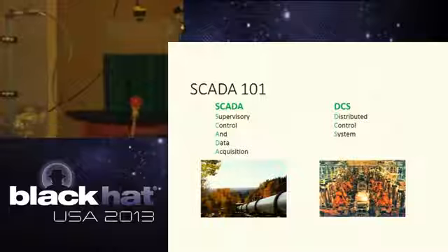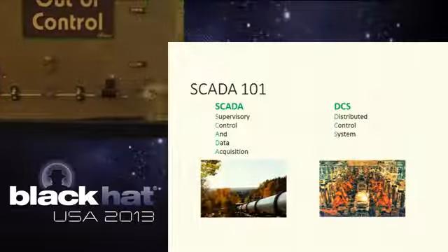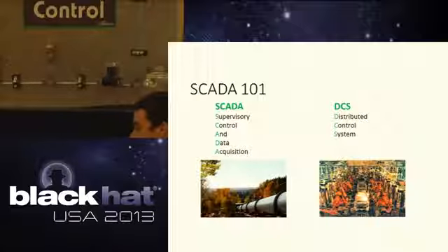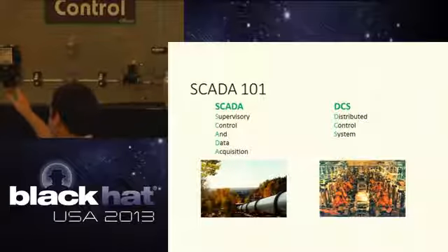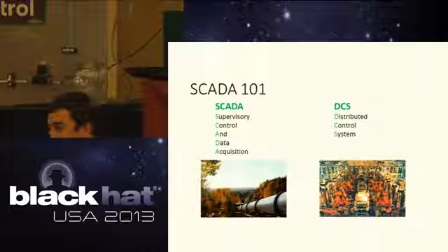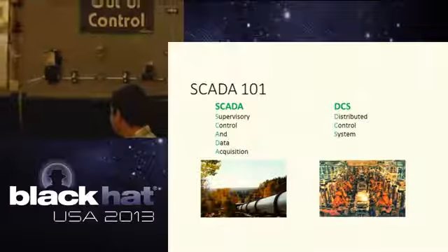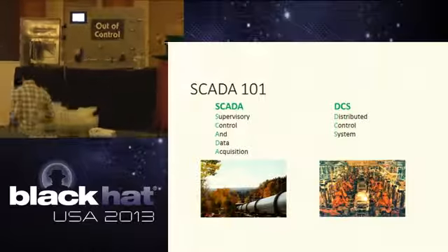One thing that we also have here is this little brass guy, and he is a pressure safety valve. You see those a lot in industry to prevent overpressures, but sometimes in production you'll have this pump and an isolation valve with no PSV in between. But we had to put one in just because we don't want to spray water everywhere. So we put one in for that.